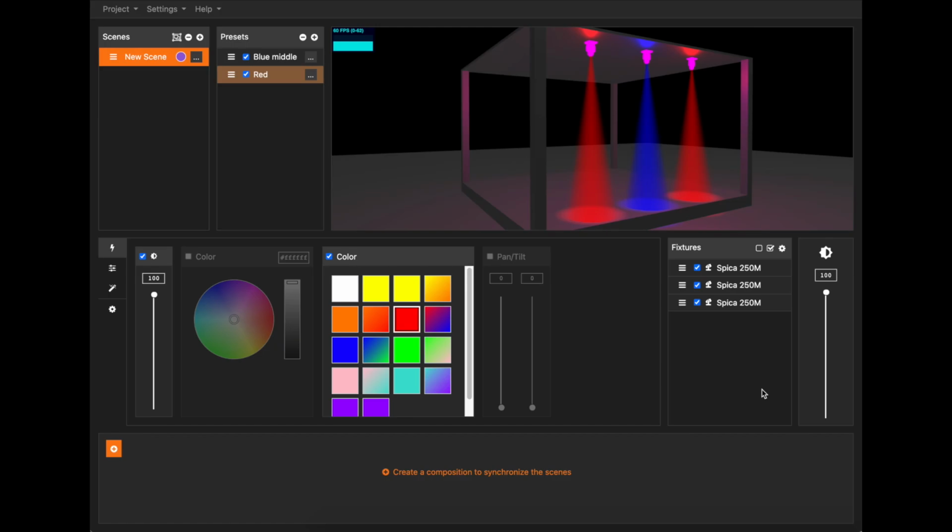We already made first contact with capabilities. Capabilities basically are just easy settings the Rocket Show designer already extracts for you and shows you in a nice way. If a fixture has a dimmer, it will be shown here. You can select the color, and for moving heads, you can also manipulate the pan and the tilt settings.